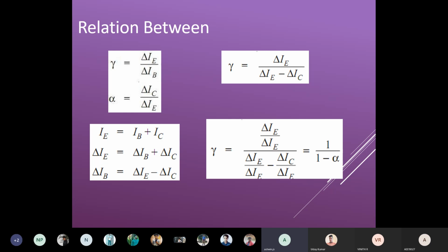That will be equal to 200 milliamps. So if 1 milliamp is passing to the base and the collector current is 100 milliamps, then if I pass 2 milliamps through the base, the current will be improved to 200 milliamps. So likewise. That's why here I am representing del IE, the change in emitter current, is equal to the change in base current in addition to the change in collector current.